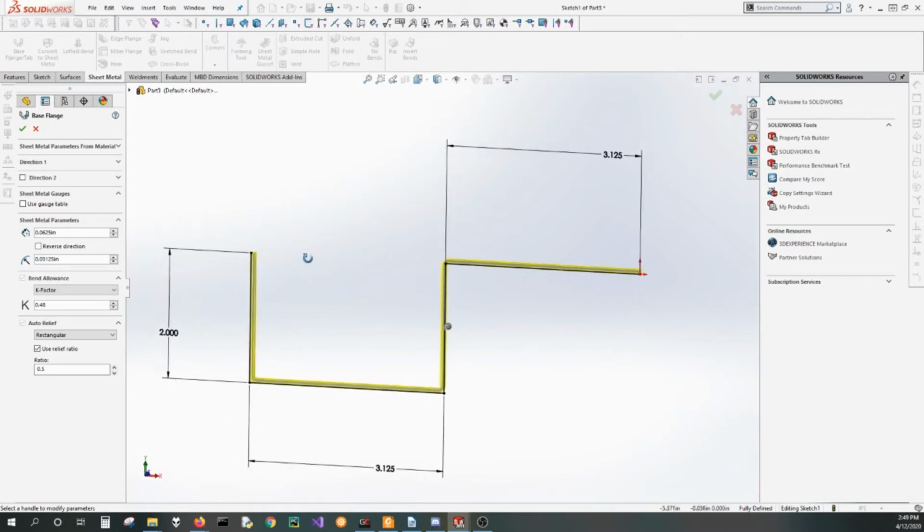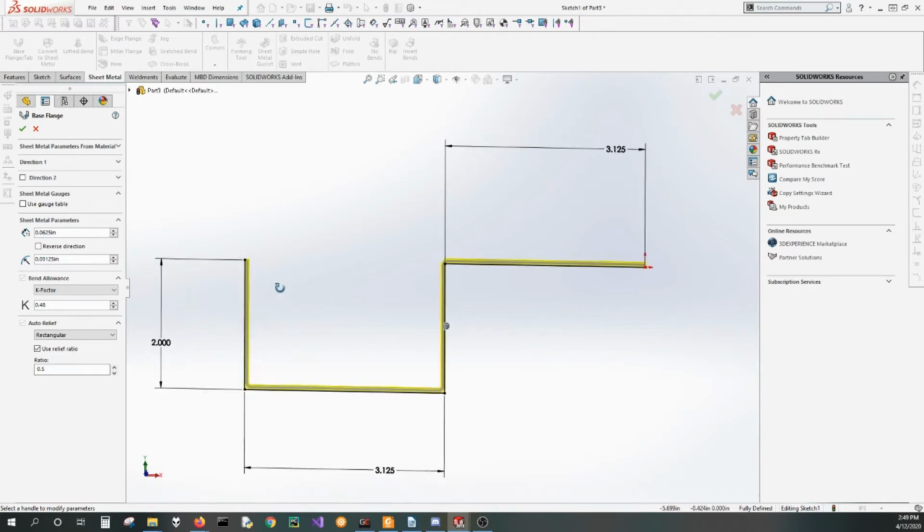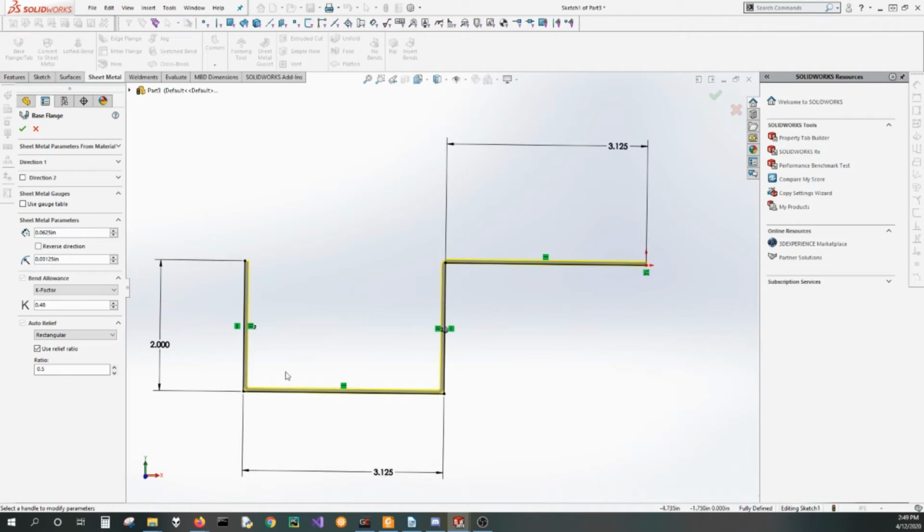And so I recommend designing parts like this so that the sketch follows the most critical dimensions of the part. And in this case, the most critical feature is going to be this width here that the battery fits in. And so this dimension is the width we need for that.